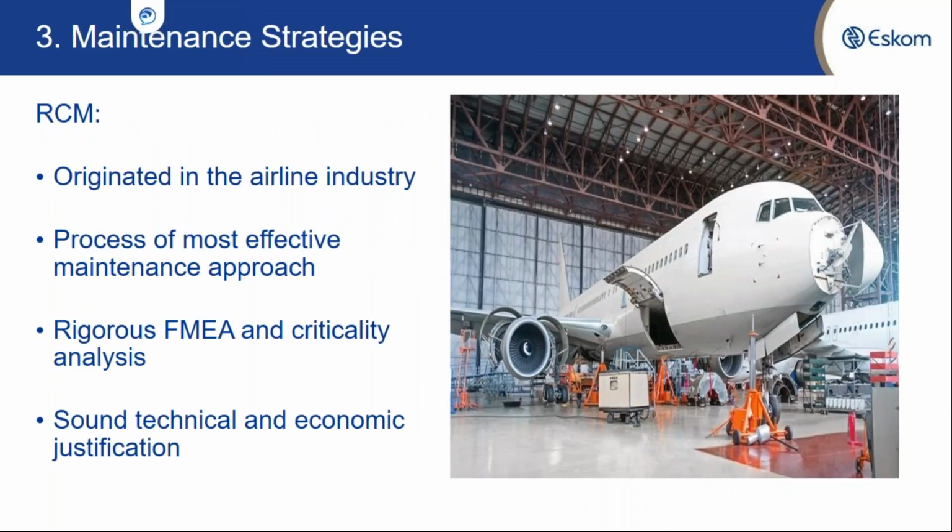Then, when it comes to maintenance determination strategies, the RCM approach leads in popularity, and it really revolutionized how we look at maintenance. It came up with a multidimensional view that failure mechanisms are different, and the maintenance strategies applied on assets should be aligned to the progression of how failure occurs.